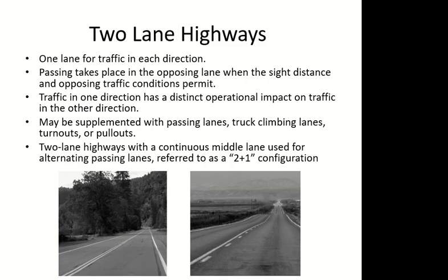Another thing about two-lane highways: the two lanes are very close to each other. We make two-lane highways on a small width of land. When two lanes are close to each other and going in opposite directions, they have an impact on the driver's speed as well. Traffic happening in a different direction has an impact on your speed. If I see traffic in one direction and that direction is very close to me, it will have an effect in my direction as well. This is human psychology, which they have found through many studies.